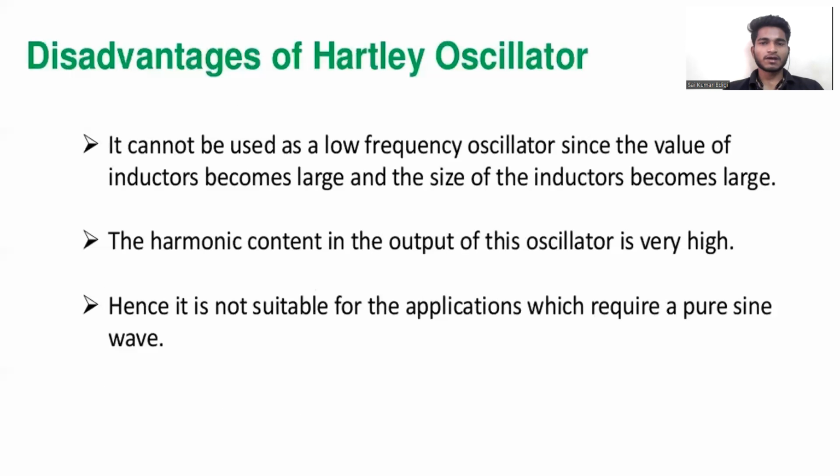Now the disadvantages of the Hartley oscillator. It cannot be used as a low frequency oscillator since the value of the inductors becomes large and the size of the inductance becomes large. The harmonic content in the output of this oscillator is very high. Hence, it is not suitable for applications which require a pure sine wave.